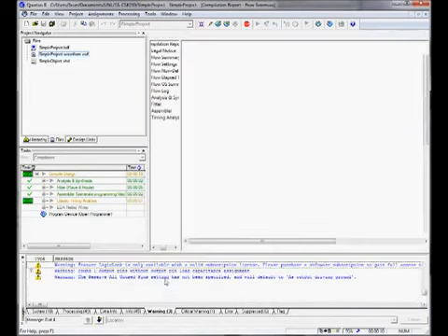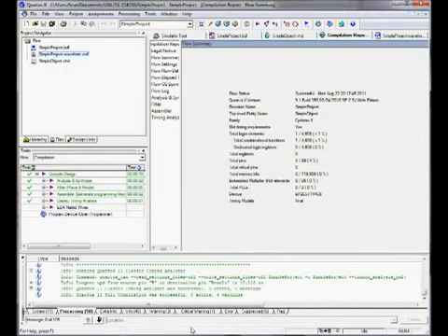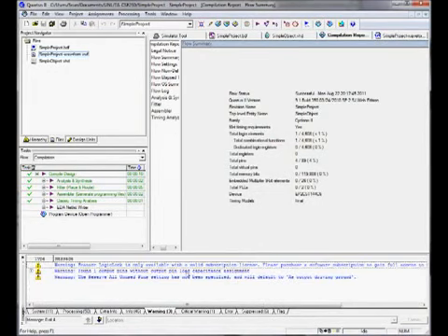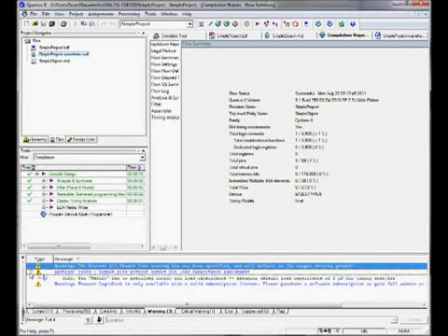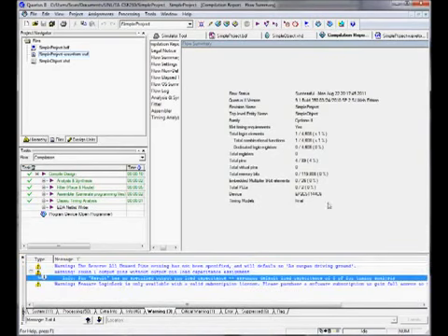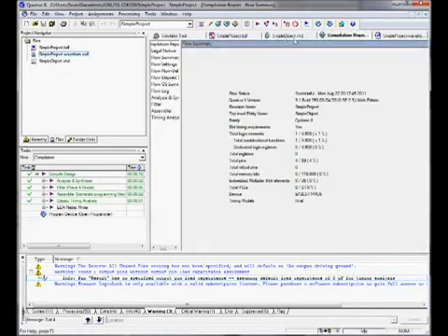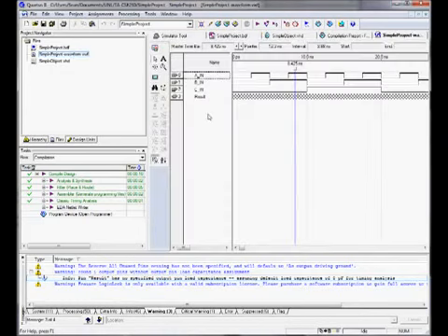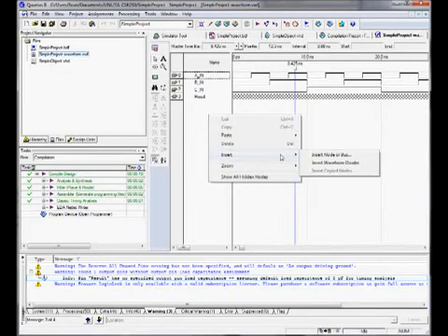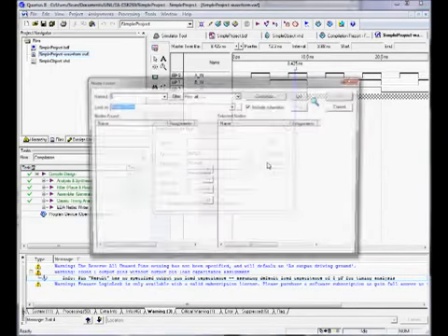And once again, we have warnings here. This is saying that we don't have a license and we have unused pins. So, result has no output capacitance. That's quite alright for us. So hopefully our vector waveform file will find it this time. So once again, we'll come into here, insert node or bus, node finder, list. Oh, excuse me, I know why this is doing it.